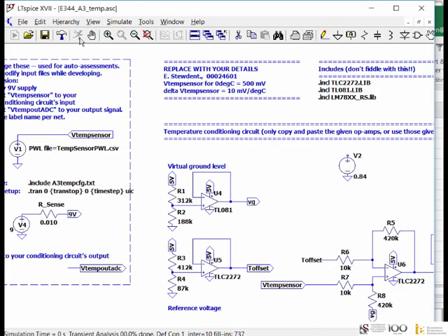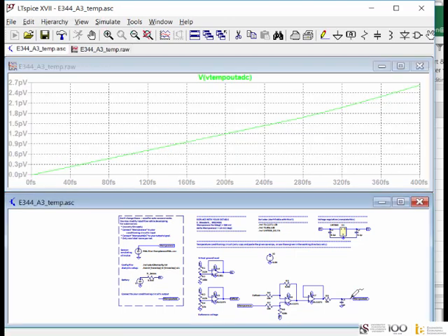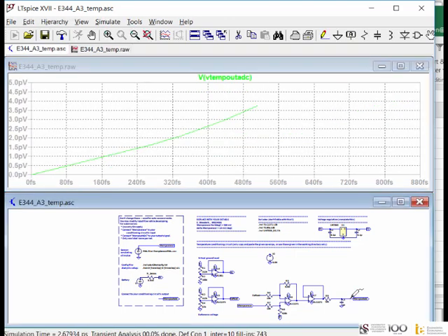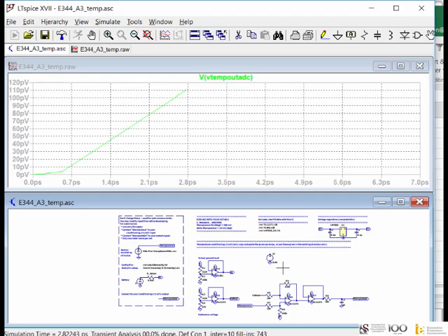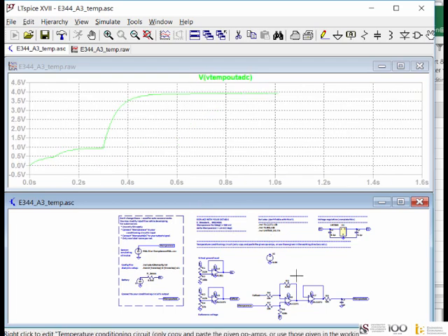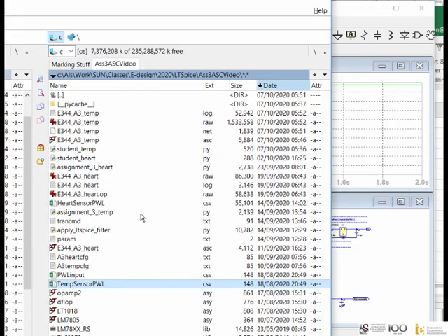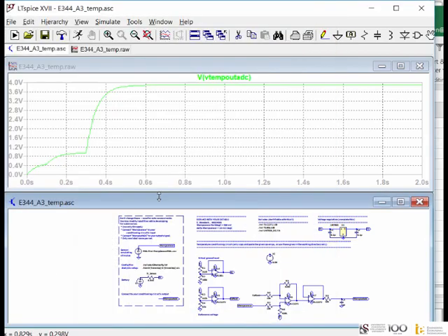So if I just simulate this, at least I can see whether it works or not. Right, and then I can check it. Is everything as I expected? Seems to be. There we go. Okay, so I've just given it a few steps, and you can see it simulates properly. So now at least I know in this circuit and in this folder that the circuit's working. So if there's a bug, I know it's not with the LTSpice file, and I know that because the Python just calls the LTSpice, it should work.